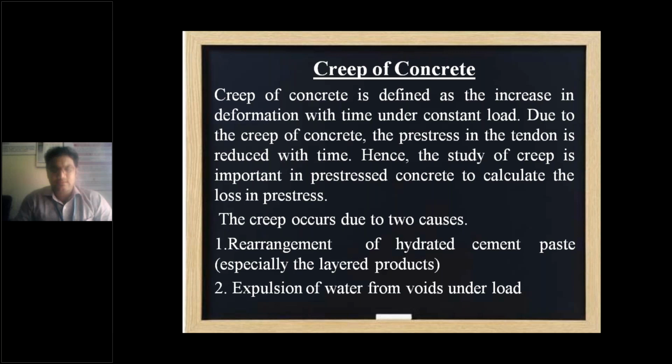Okay, so this study is very important in prestressed concrete, to calculate the loss in prestress. In the second unit, when we start our second module, the first content itself is the losses in prestress. In that you will understand very keenly the importance of creep of concrete, right? So that is how creep plays a vital role. Concrete should have very good creep behavior, so that the concrete can withstand the loads and keep the prestressing of that particular tendon for a lifetime.